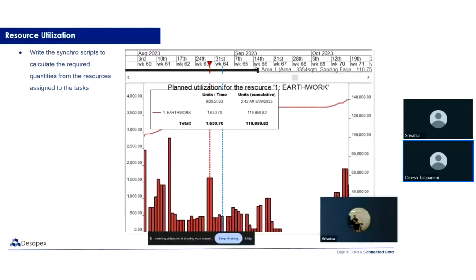So let's start with laser scanning. As for the second part, it is basically a LiDAR technology used to create a 3D representation of objects. What the laser scanner does is eject lasers; the beams hit the object and reflect back. It collects millions of points around the object and gives you point cloud data. With the help of that point cloud data, we develop the 3D models. So that's basically laser scanning. This is reality capture, the entire process. What you're seeing here is a Leica product, the RTC 360.